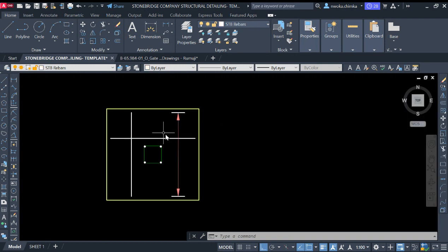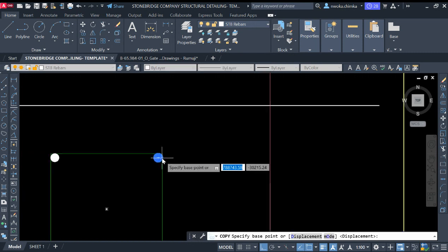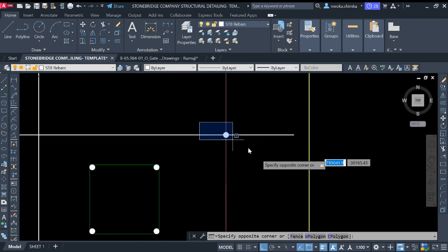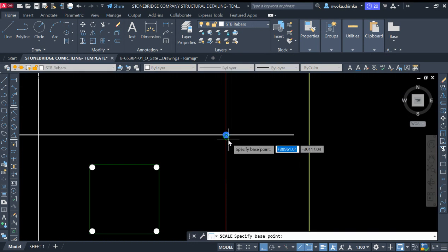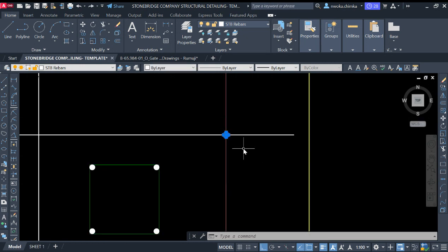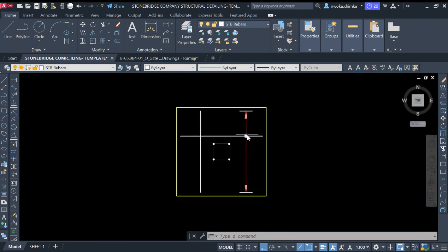So right now we have established this, so we will now also copy this right now for this callout, to call out this with this reinforcement. This is like a bulb, to put it here, and then blow this up by 2. So we scale this up by 2 using our SC. Let me review what I just did right now. I just select this right now, type SC and then enter, and then click at the midpoint here and type 2, which is I want to blow it up by scale by 2. So I now enter, and this is what we have right now.